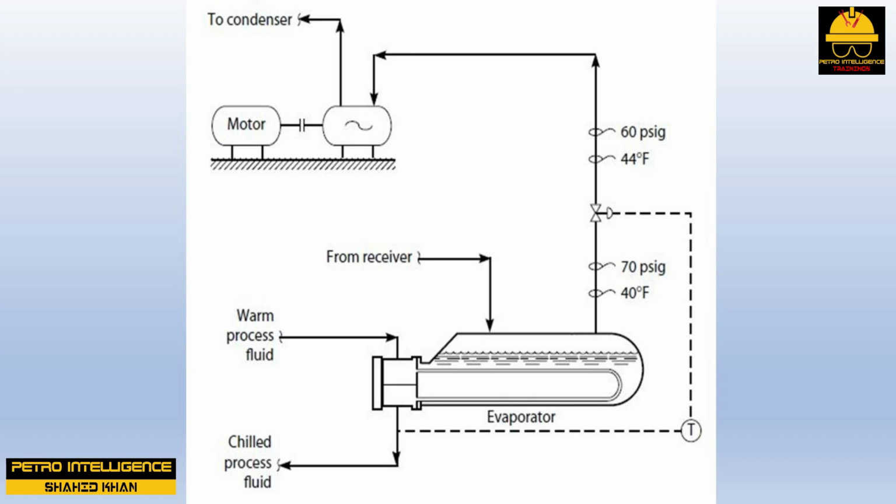And this statement is true regardless of whether the compressor is a reciprocating or centrifugal machine, or fixed or variable speed. It is the condenser temperature that determines the compressor discharge pressure. Lowering the compressor discharge pressure can be achieved by providing cooler water to the refrigerant condenser. But how does this affect the horsepower load or electrical power demand on the compressor's driver? It depends on how much the refrigerant vapor flow increases, as the compressor discharge pressure is reduced.